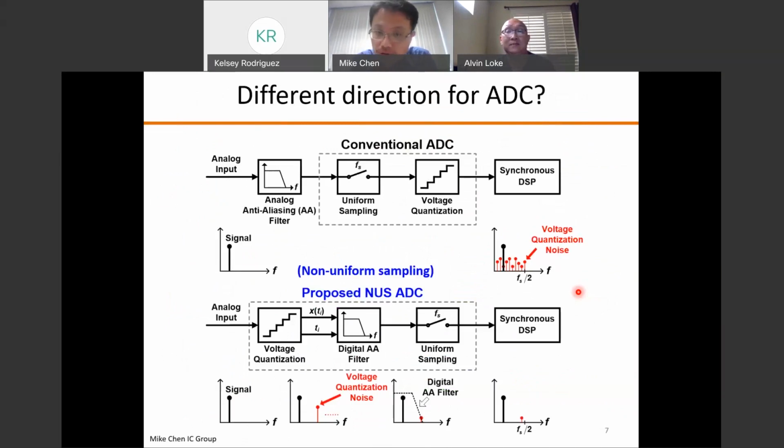So in terms of designing the circuit to be more linear, you can just borrow the conventional wisdom of how you design your ADC or your receiver. I don't find that part too different. However, I do want to point out something related to the interpolation I mentioned earlier. So far, we mostly focus on zero-order hold because that's the easiest, crappiest, and simplest interpolation. If you are able to use iterative algorithms or higher-order interpolation algorithms, you could also further reduce the distortion due to that interpolation.